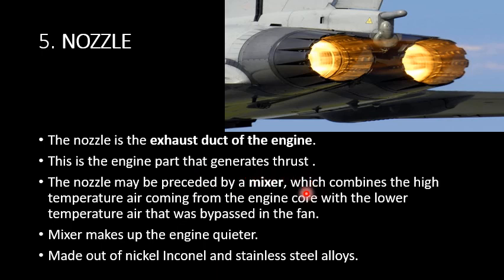The nozzle may be preceded by a mixer, which combines the high temperature air coming from the engine core with the lower temperature air that is bypassed in the fan. The mixer makes the engine quieter, and the nozzle part is entirely made out of nickel, Inconel and stainless steel alloys.